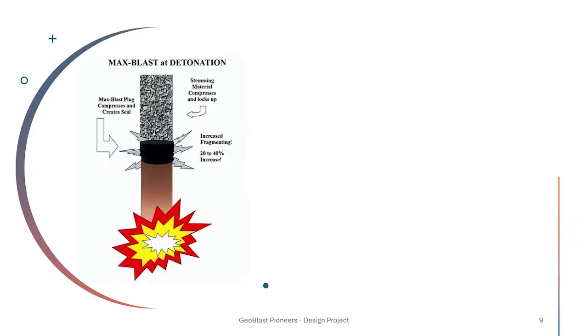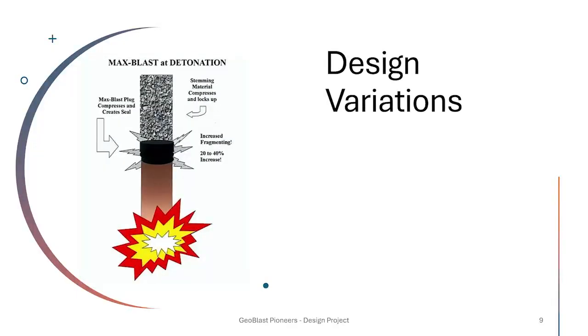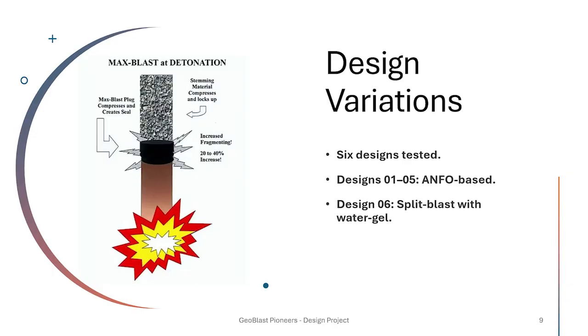In total, we developed 6 main designs. Designs 01 to 05 were based on ANFO with different charge amounts, burdens, and spacings. Design 06 used a split blast technique with water gel explosives only, aimed at better control and safety. Our objective was to compare these patterns for the best fragmentation, lowest vibration, and most economical outcome.